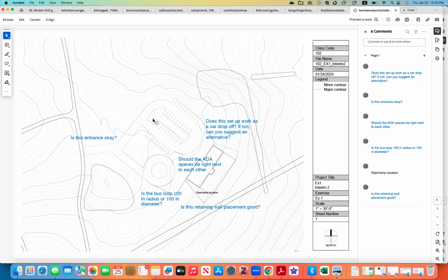We're pretty close here. 50 feet, double check that. Yeah, I just did. It's a little long. Okay, I don't know how to fix the entrance and also make it more than 50 feet away. Well, your line will likely be curved like this, and then you make a polyline following the boundary and make a 50-foot offset. Okay.